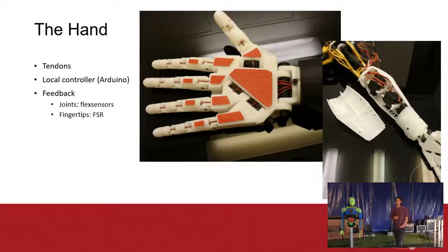The other thing is, because I'm using ROS and because it is developed to be a very professional system, it requires feedback. Feedback is, it requires to know the position of the joints at any time. So in the original design, you would only send a pulse width modulation signal to the servo motors for them to move to a certain position.